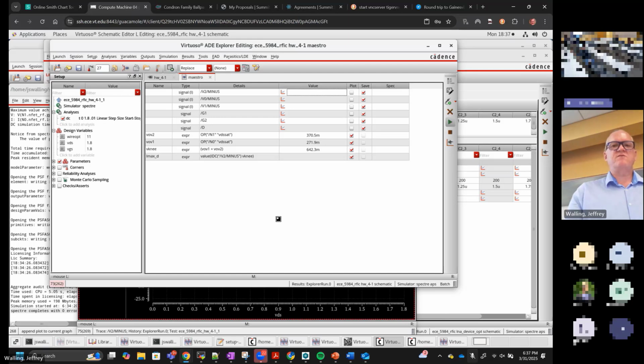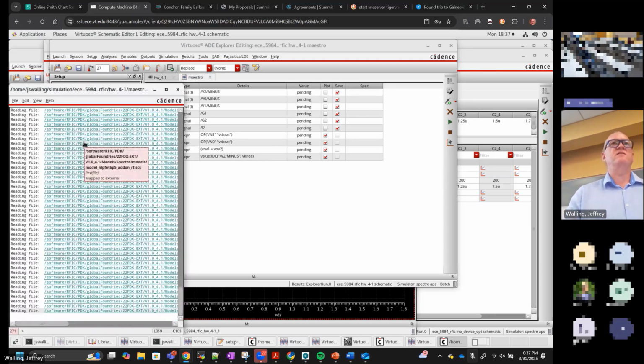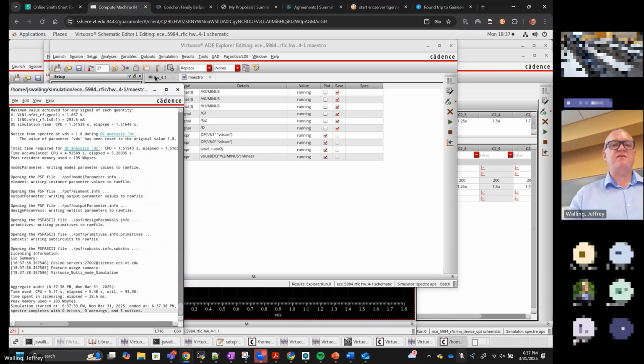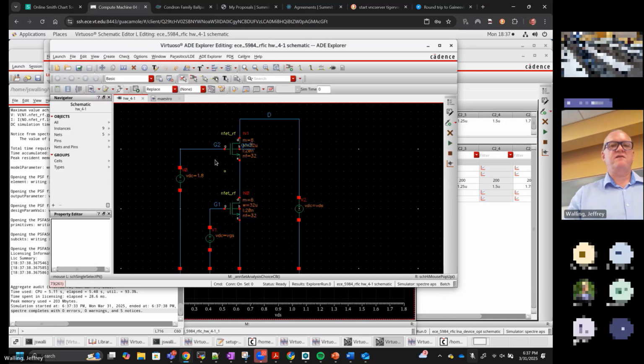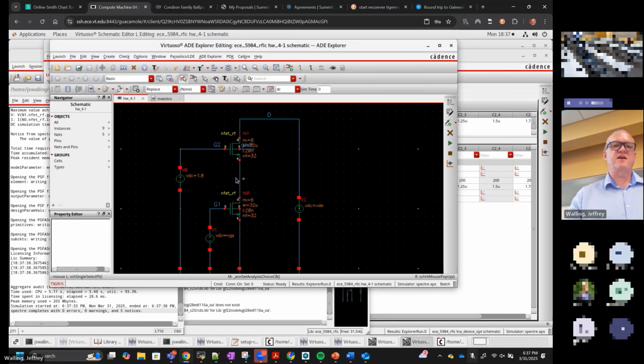Yeah, in this case, if I set VGS to a different value, you're going to get a slightly different result. But the primary difference here, in this simulation, is that we have set both gate voltages at 1.8 volts. So there's a different threshold voltage because of that body bias. And yes, you're right, this upper device also sees a different source voltage.